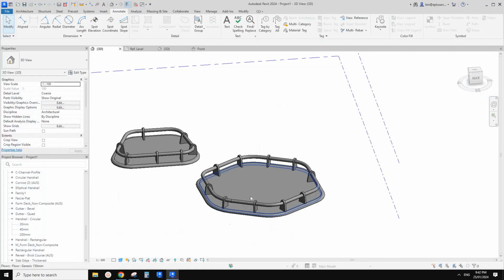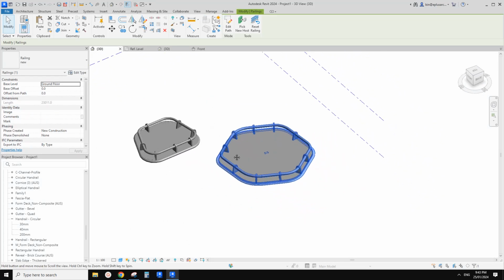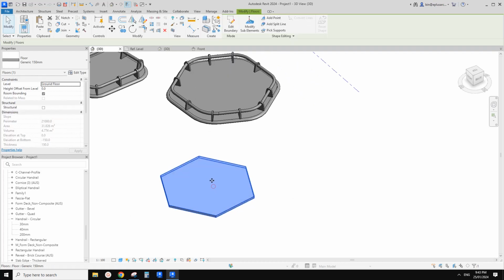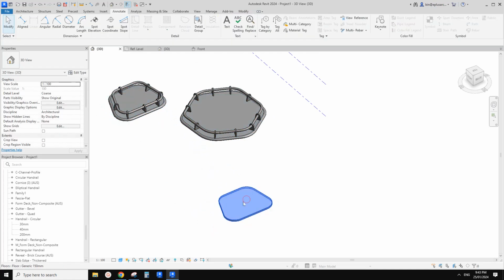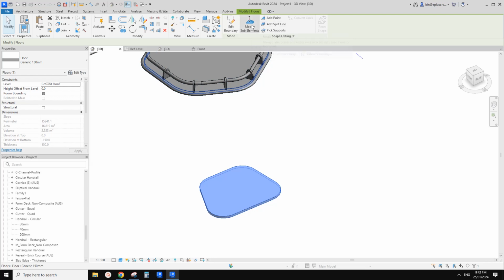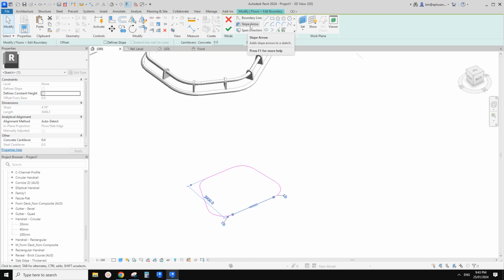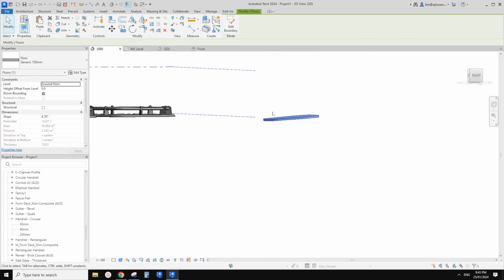And yeah, the good thing about this is sometimes, so let me just create another one. So sometimes you might, hang on. Maybe I'll just copy this one. I don't want to do it again, so maybe copy this floor. You can also edit boundary, give it a slope. Where is it? Define slope. Okay, so finish. So now you can see this is on a slope, right?